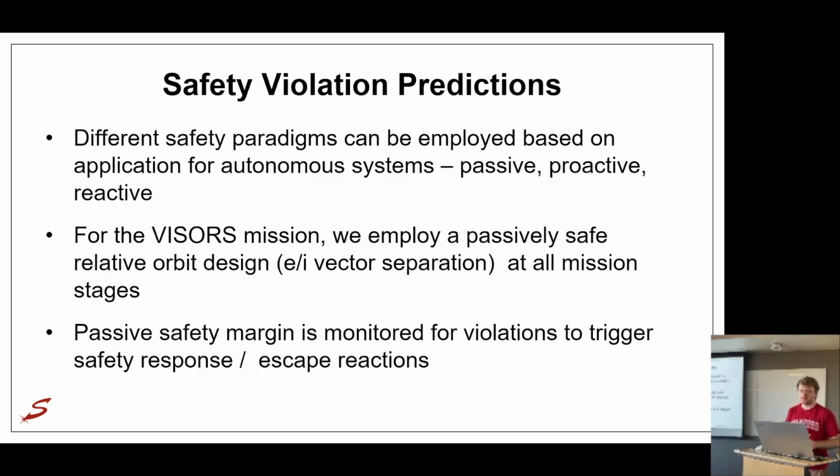A proactive system is somewhat in the middle, where you are on a trajectory where you ensure that your control trajectories can be escaped from efficiently or with reduced control capability, so that you could potentially find yourself only on trajectories which you could escape from with a single maneuver if you needed to.